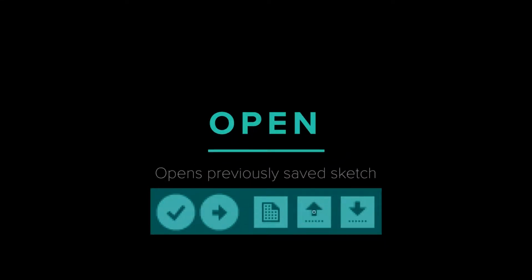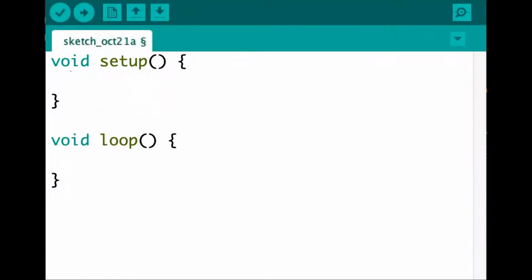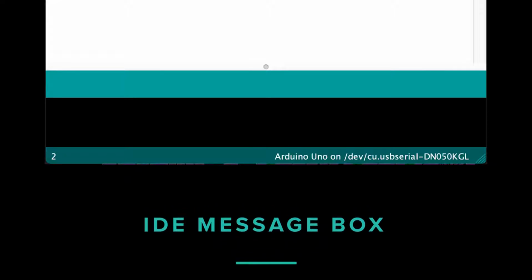Next is Open, where you can search and open any previous saved sketches. And lastly is Save, which is where you can save any code you've created in that sketch. Each blank sketch will have two preset functions that are essential to every sketch: void setup and void loop. Don't worry, we'll talk more about this later in the video. And at the very bottom of your sketch is the IDE message box. This will give you the status of your code or whether an error was detected.